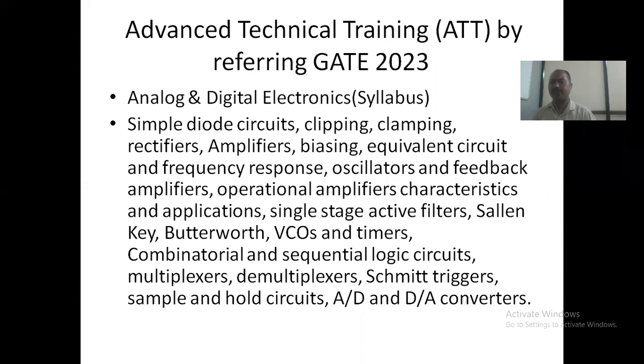Then the rectifier. You know that a rectifier is the device which converts AC voltage into DC voltage. According to our need, we use different types of rectifier. Basically it has only two types, the half wave rectifier and the full wave rectifier. A half wave rectifier uses only a single diode for the conversion of AC into DC. One of the greatest disadvantages of the half wave rectifier is that it has maximum ripple.